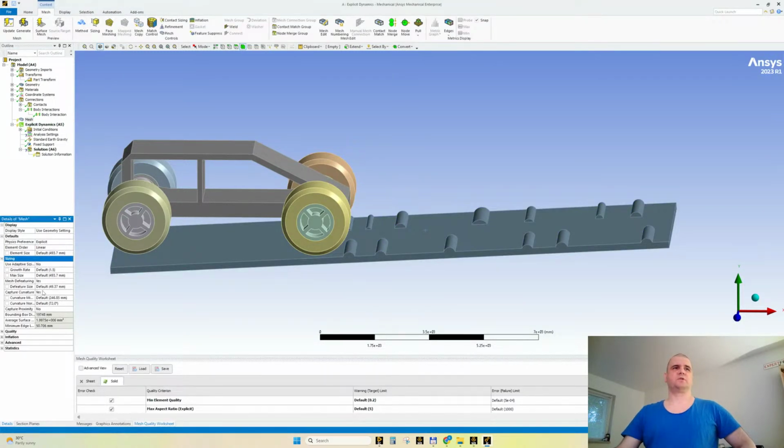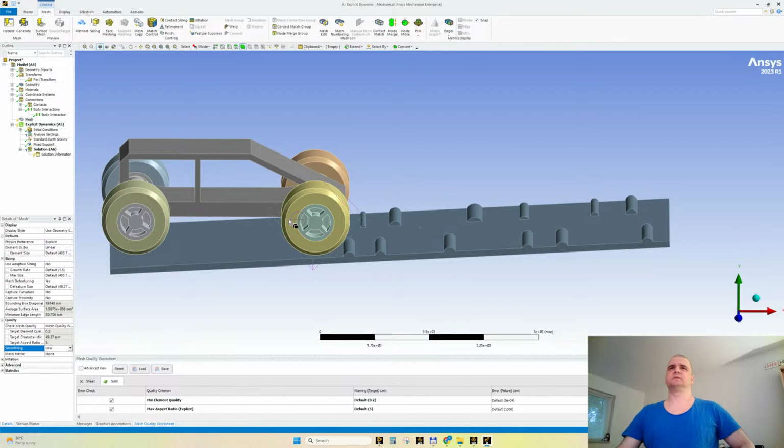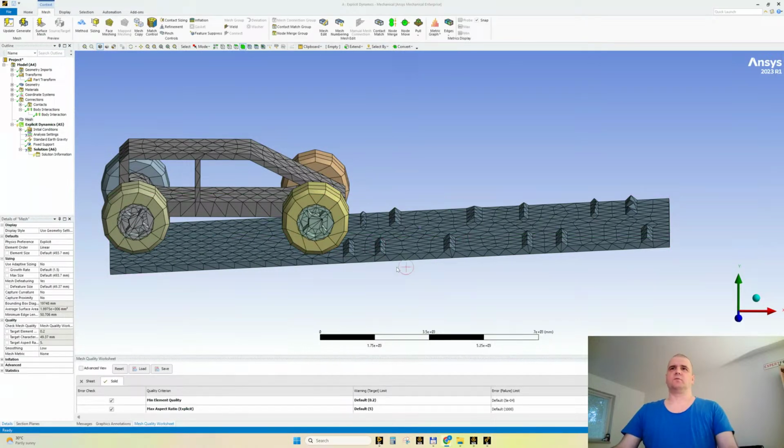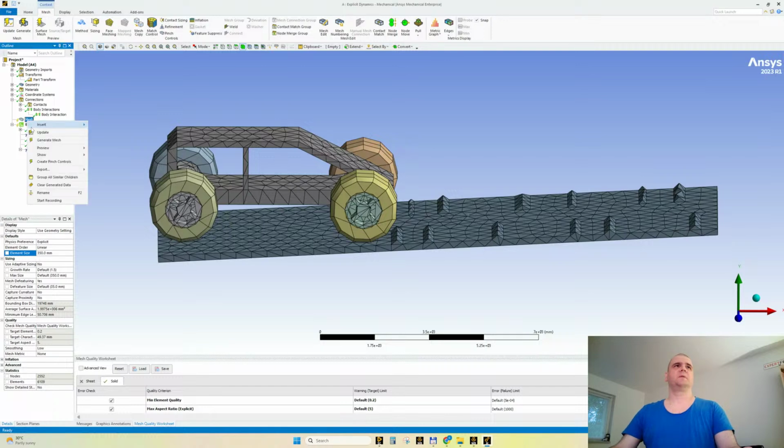Here for mesh, I will choose capture curvature now, and for quality, I will choose smoothing low to have a very coarse mesh. The focus will be on the FEA to make it work, not on the refinement and other stuff. So coarse, but not so coarse. Instead of 493, let's choose, I don't know, 350 millimeters.